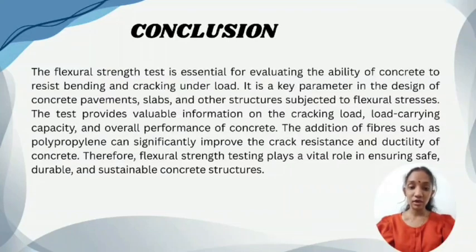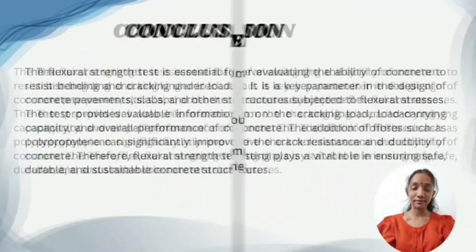The addition of fibers such as polypropylene can significantly improve the crack resistance and ductility of concrete. Therefore, flexural strength testing plays a vital role in ensuring safe, durable, and sustainable concrete structures.